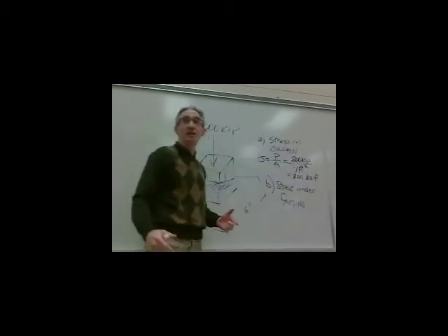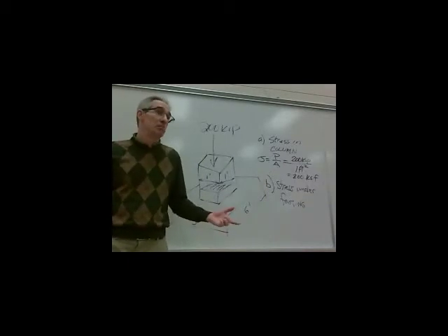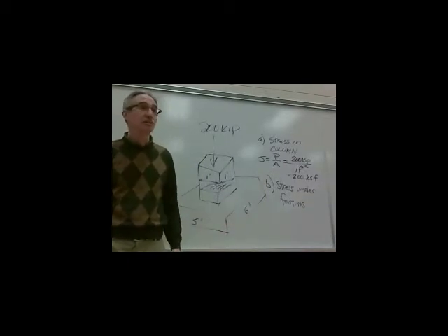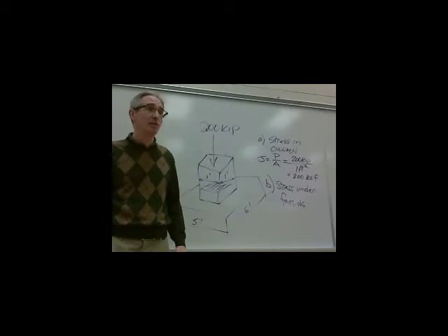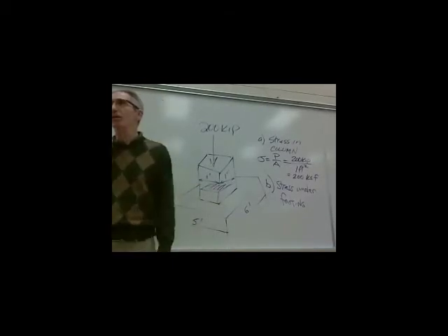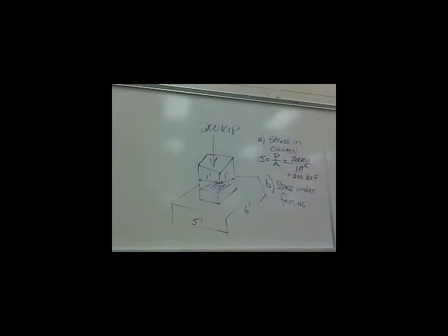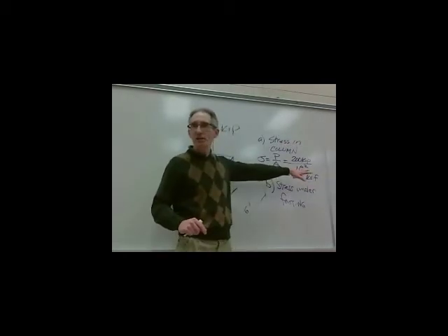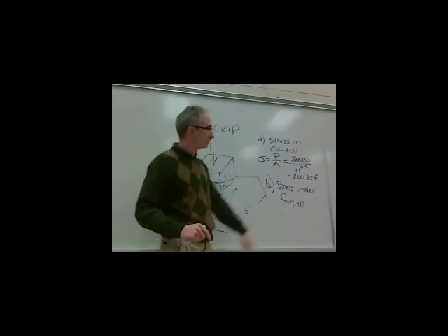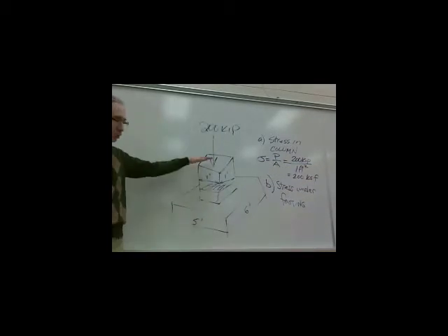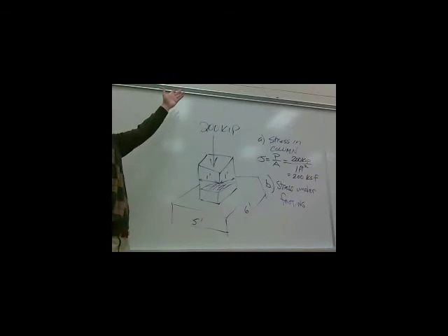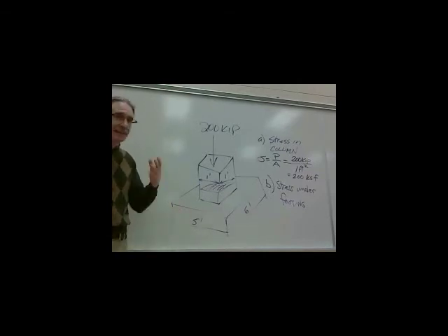KSF. Now, is that a lot? Well, it depends. I don't know what material we're talking about. I mean, we really didn't say what material we were talking about. This could be concrete, could be wood, could be steel, could be aluminum. That's going to differ in all those cases. It would differ if this was a short column, which I said it was, and a very long column. Is that stress going to be too much? I don't know. That's what you get into as you start getting into the design.